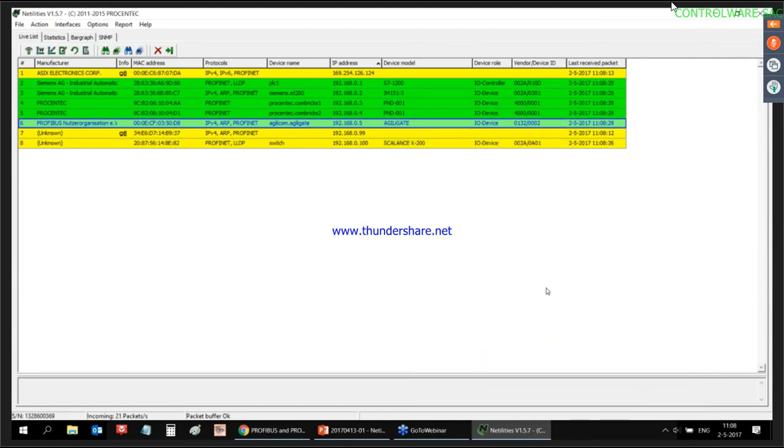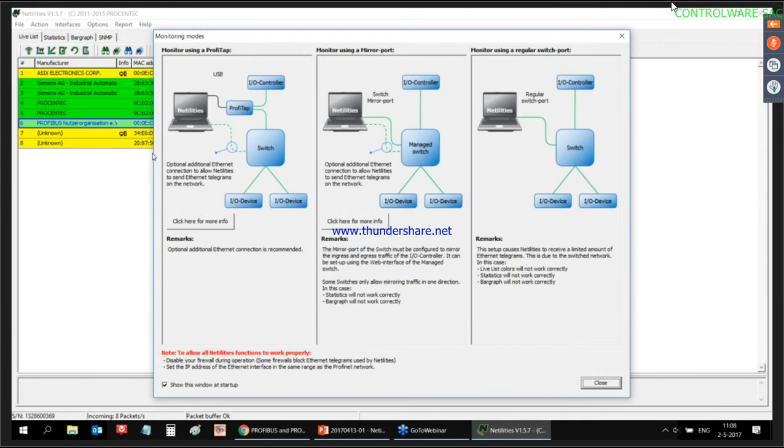So we have another question from Corey, on how to explain the connection for the setup. In this configuration, we can show you live, but I will try to explain here with the live list and maybe with the topology. We have a Siemens 1200 PLC connected to a Siemens X208 switch, which is a fully managed switch certified for Profinet.